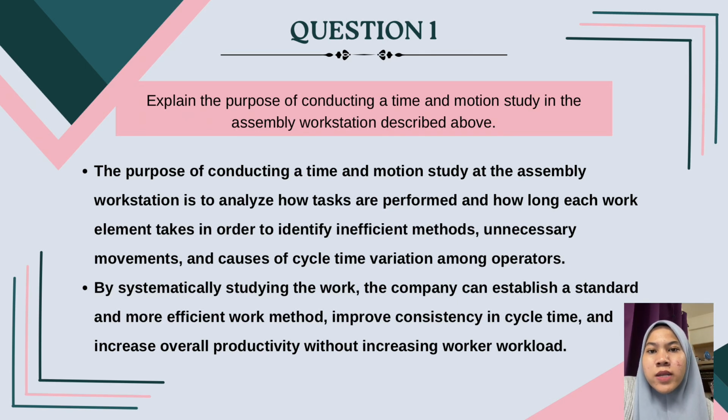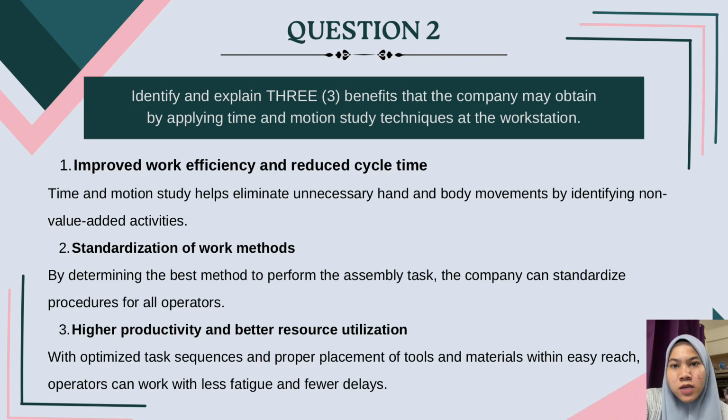So the purpose is to analyze how tasks are performed and how long each work element takes in order to identify inefficient methods, unnecessary movement and causes of cycle time variation among operators. Second question discusses the 3 benefits that the company may obtain by applying time and motion study techniques at the workstation. First, the company can improve work efficiency and reduce cycle time. Time and motion study helps eliminate unnecessary hand and body movement by identifying non-value-added activities. This allows operators to perform tasks more effectively, leading to a shorter cycle time.